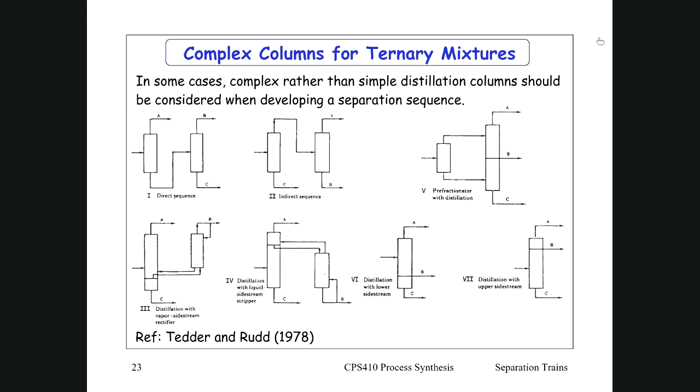Okay, good. Now with a RadFrac, you can actually do this thing of taking off a side stream from whichever tray that you like, and you can attach the liquid that's coming back. You can replace it on top of any tray that you like. So RadFrac is an extremely powerful Aspen tool. We just haven't done that particular one.